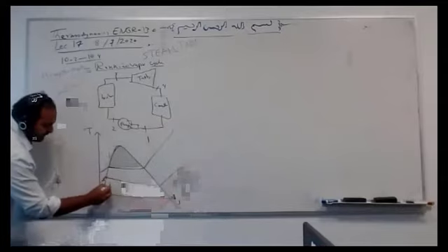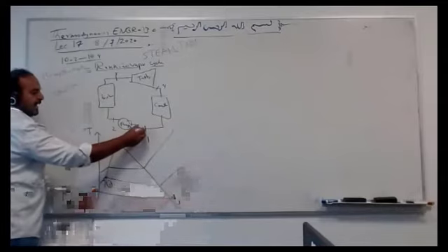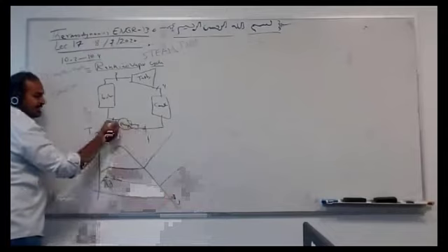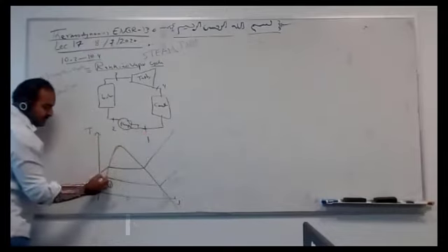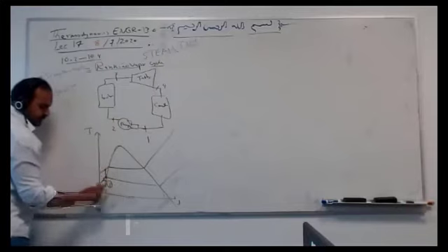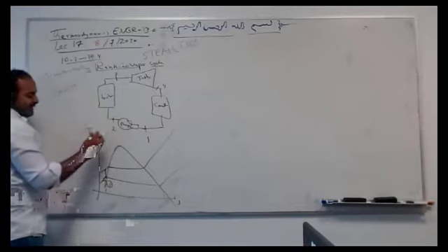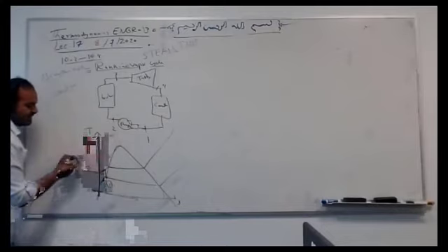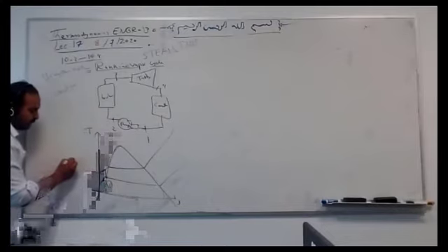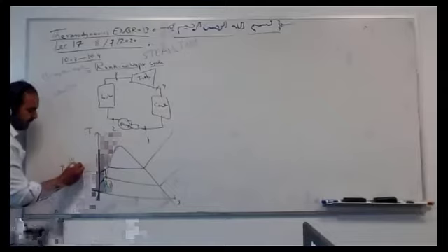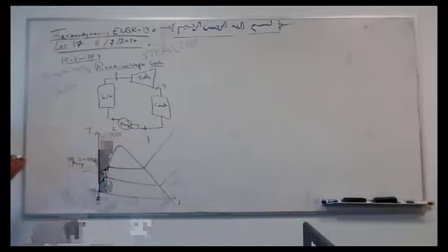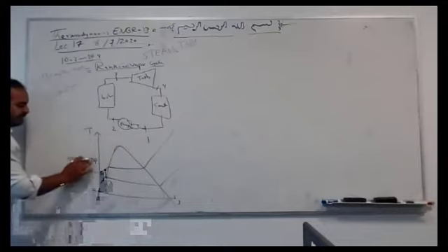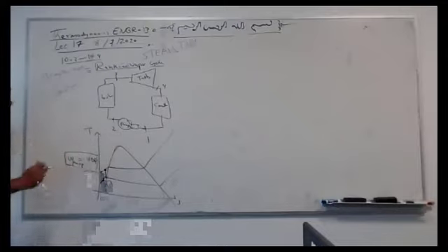So what happened? Here I'm at 1, before the pump, I compress. Everything is reversible. This is isentropic, delta S equals 0. Because it's a fluid, a liquid, we assume constant volume. So you can use the work in the pump as minus VdP. We did it before: the reversible work given in a pump is VdP. That's it, because it's reversible and it's a pump.